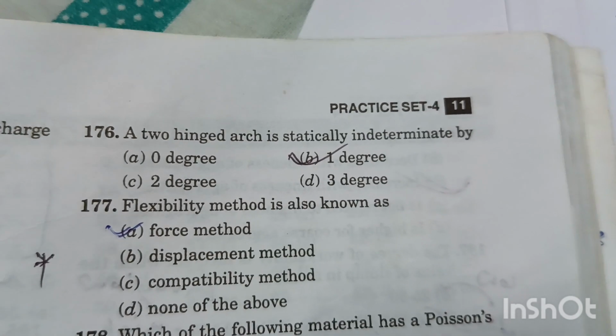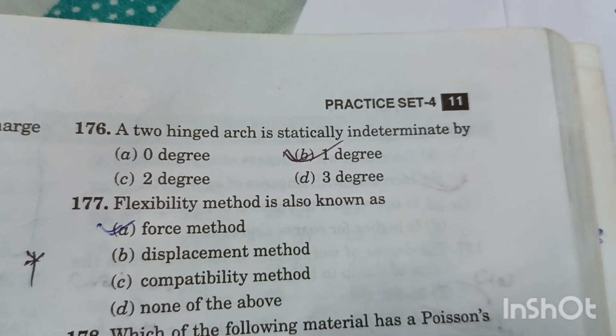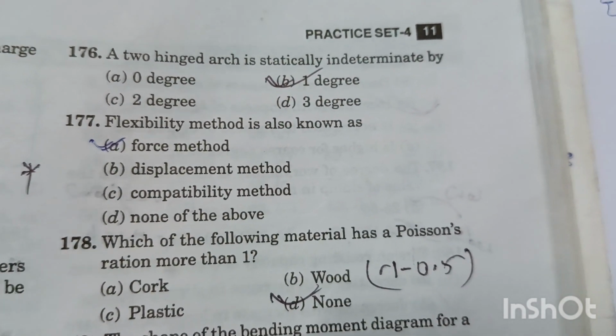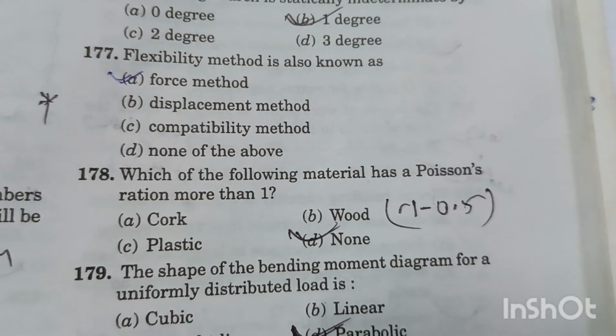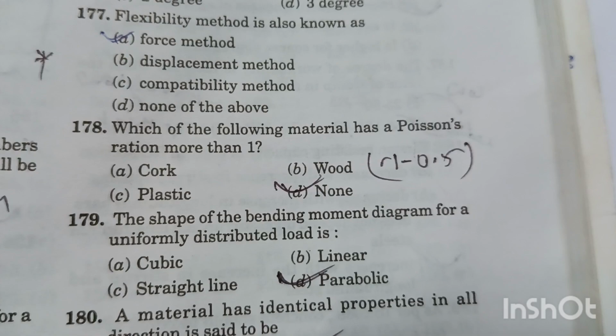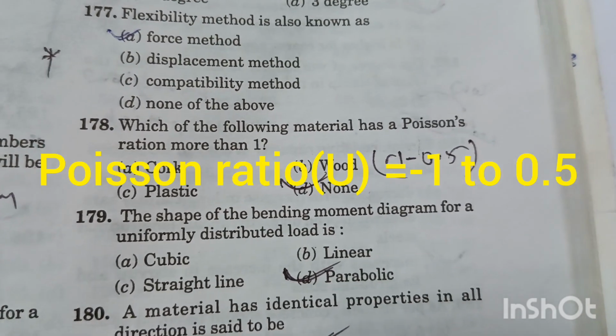So the arch is statically indeterminate by 1 degree. Option B is the right answer. Question number 177. Flexibility method is also known as force method. Option A is right answer. Question number 178. Which of the following material has a Poisson ratio more than 1? None of the above. Option D is the right answer because Poisson ratio has a value from -1 to 0.5.